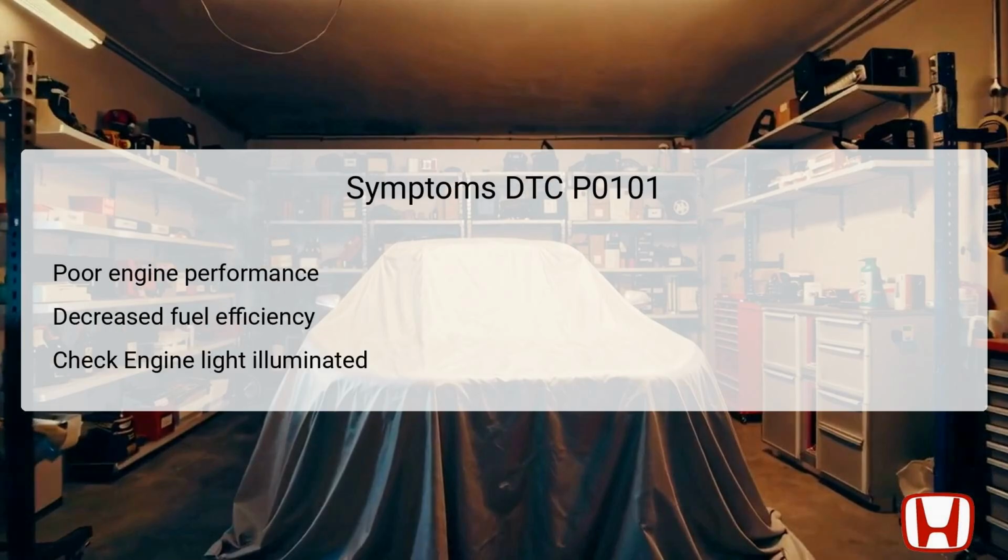The DTC P0101 code may present several symptoms that indicate underlying issues. One common symptom is poor engine performance. The vehicle may hesitate or stall due to incorrect air-fuel mixture adjustments.